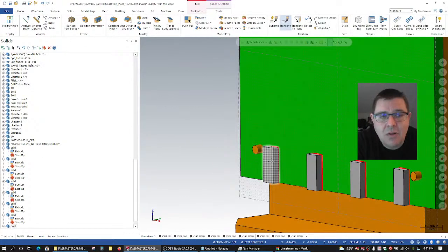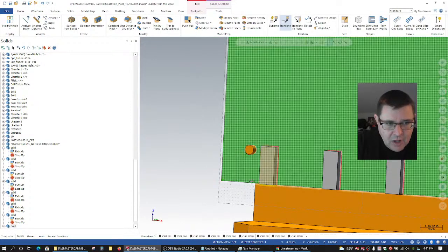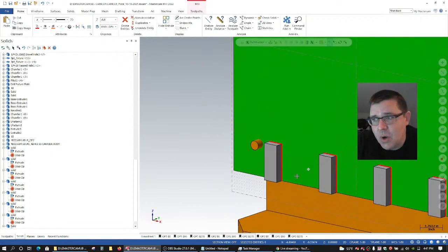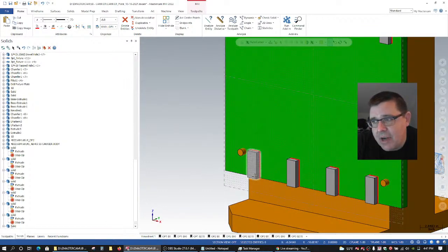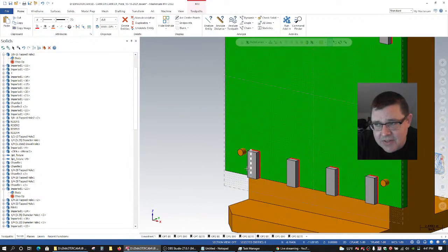This is going to be 12, and a lot of times, if I'm doing an avoidance geometry, so the complex solid simplify, I simplify what I can, right? So if I'm doing an OptiRough operation and I'm doing an avoidance geometry, I'm not going to select this entire double set of two models that has all those faces.